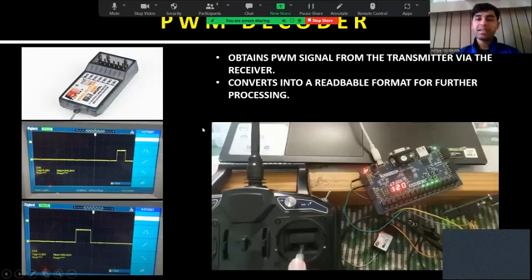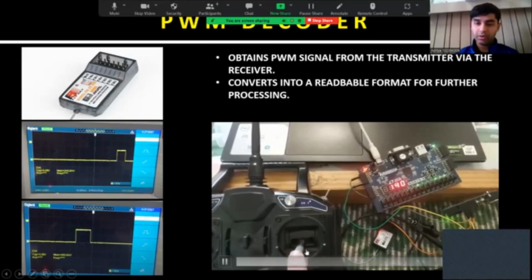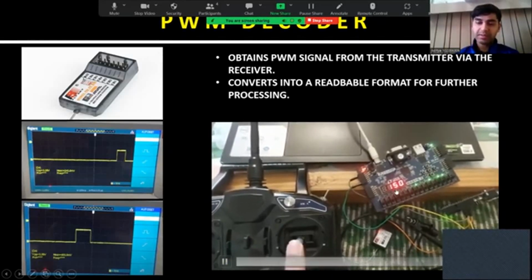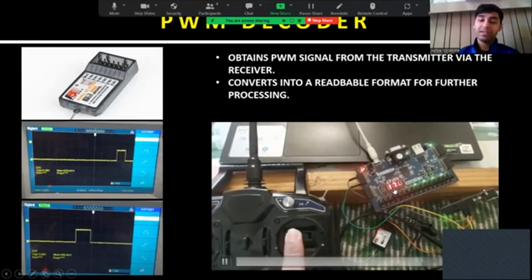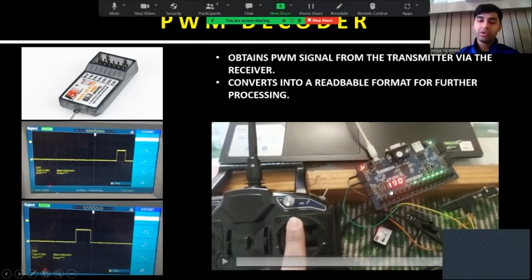And this output is then processed by the module and converted into a format which is as follows. So here we can see that when we push the stick up or down, the PWM signal that has been transmitted is displayed on the 7-segment display of the FPGA. Here the pulse width is being displayed in microseconds divided by 10. So 190 corresponds to 1900 microseconds.